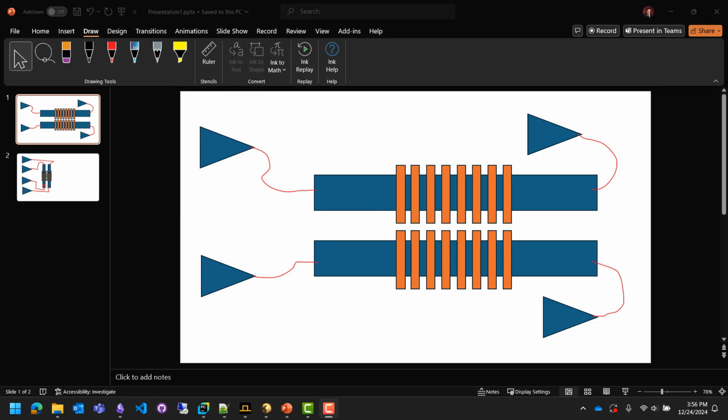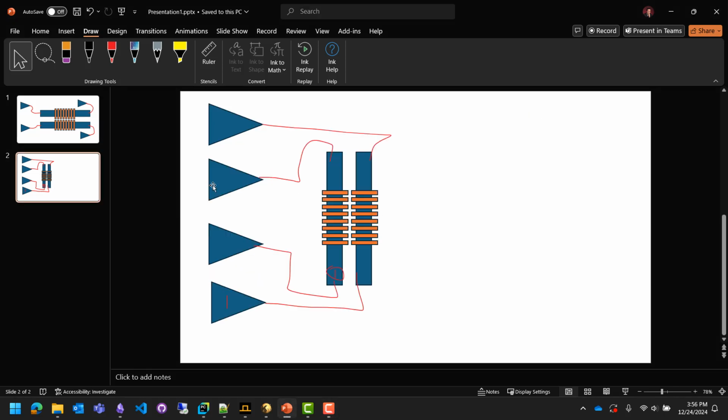So what we're looking to aim to do right now is to create something like this image shown on the screen here. We want to take our contra-directional coupler device that we made in part B for advanced P cells and place it. We then want to place 4 more grating couplers and connect the grating couplers using waveguides to our device. And then the final result should look something like this, where we will have our grating couplers on the left, and then we'll also want to rotate our device by 90 degrees so it's vertical, and then connect the waveguides as such.